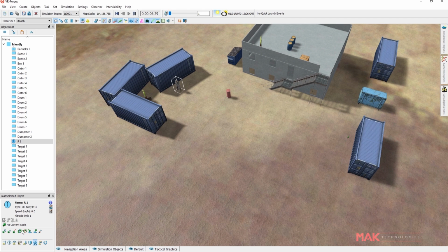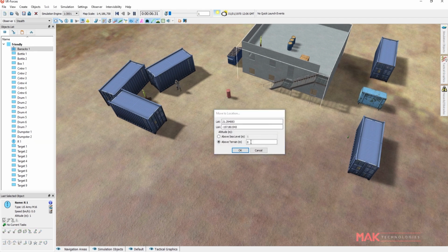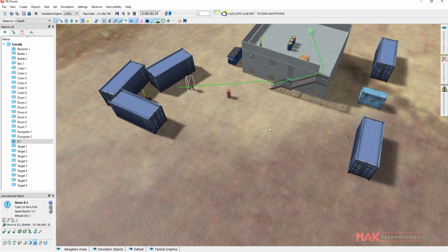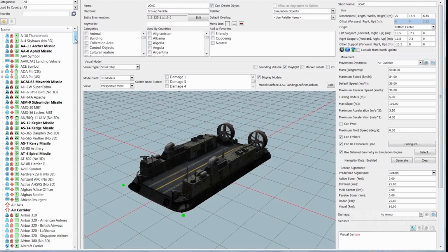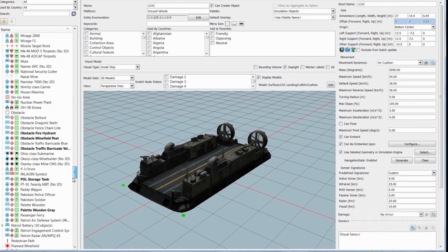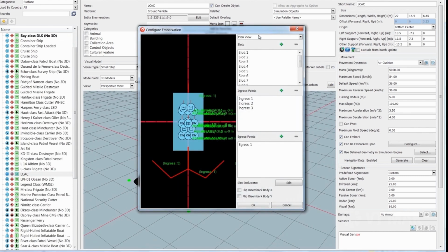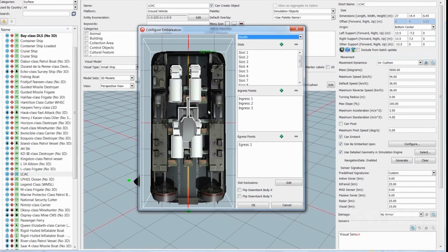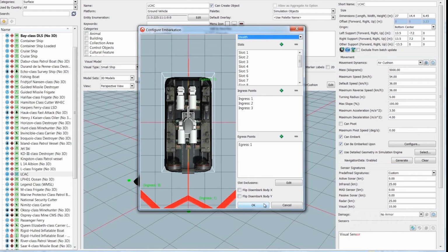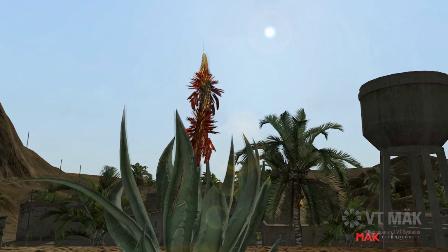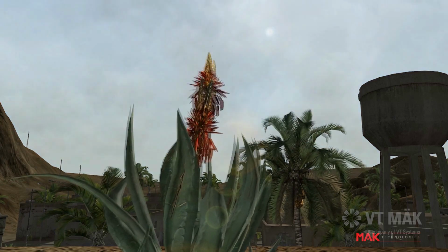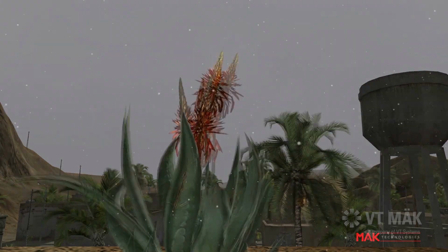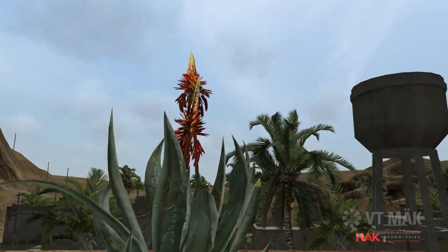For modelers and training instructors, without programming skills, they can configure and set up VR Forces to model specific doctrine and user roles. Use the editors to configure new models, specify the force structure and allegiance, assign weapons and sensors, define physical properties and motion dynamics parameters, set up the environmental conditions, weather, time of day, even tweak the terrain database to improve the look and add scenario-specific content.